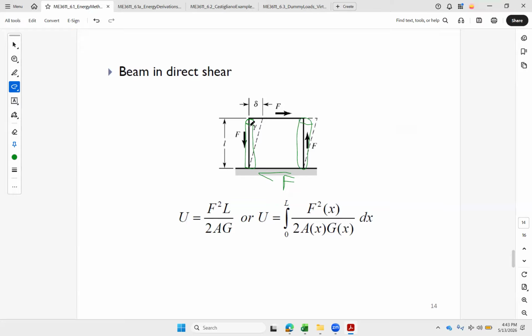So if this thing wants to twist over to the right, if I push up on the right bar and I pull down on the left one, I could torque it back to the left. Torque it back counterclockwise. That would mean this one's going to be in compression, this one's going to be in tension. But at the end of that bar, that force gets passed on to the top member. All right.